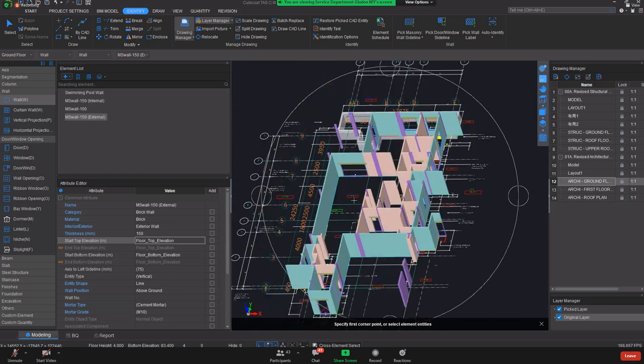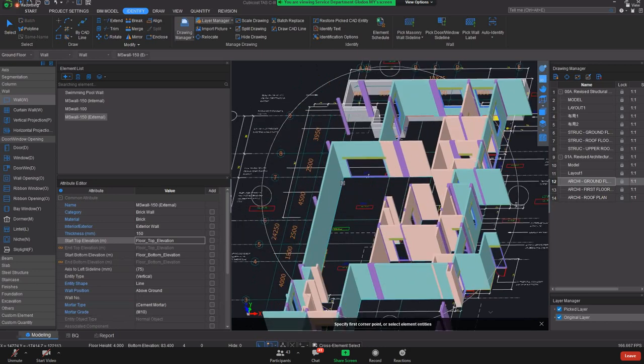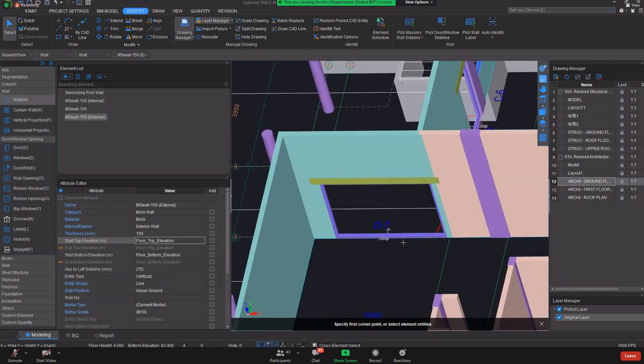If it's not necessary, and it actually happens with the beam, you can just delete the lintel. But what I know is if there is a beam directly at the opening, it actually won't generate the lintel for it. Just to be on the safe side, you open the 3D to check whether the lintel is being generated at the opening just below the beam.